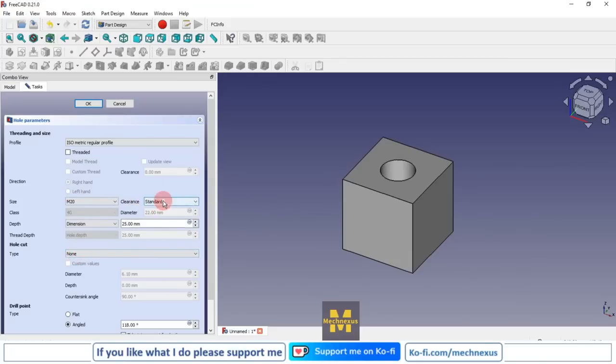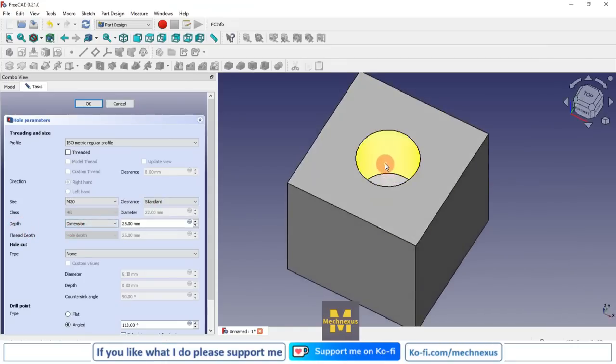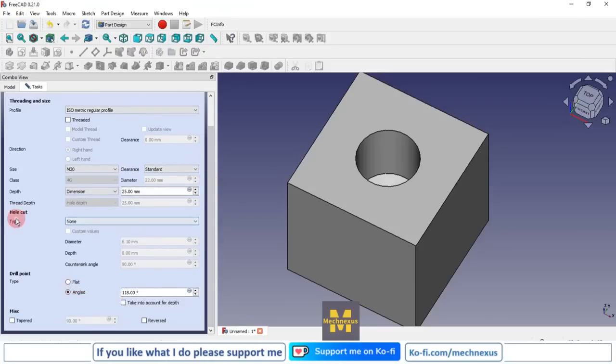Here is a clearance type, close, wide or standard, so we will keep it standard. Depth is for the hole, so for depth we will give 25 mm, and in the hole cut, there are multiple options here, but we are giving the M20 threaded hole. Angle is 118, which is a drill angle. If you want to keep it flat, we can also keep it flat.